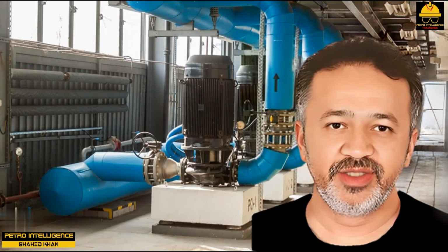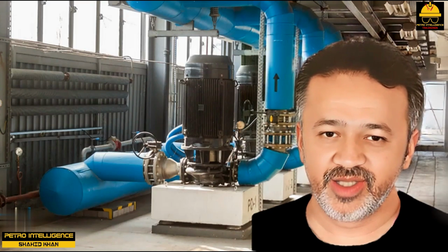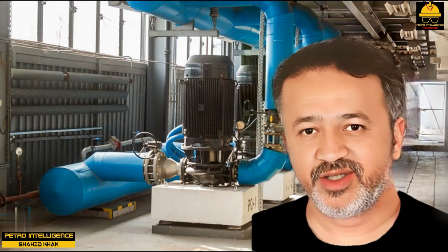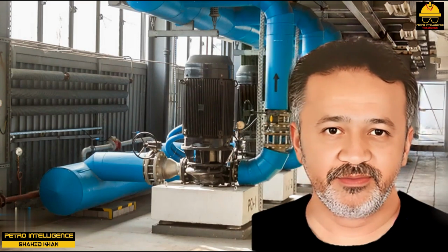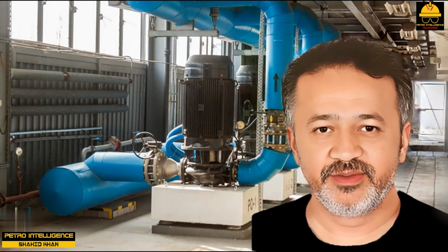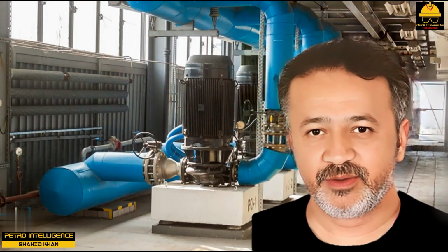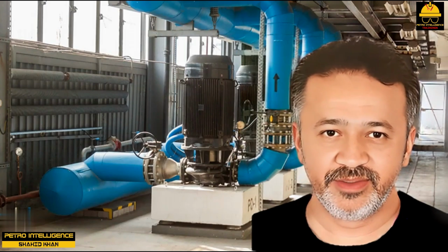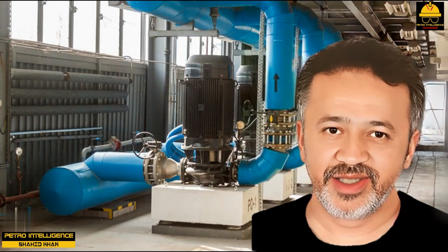An easy way to witness hydraulic surge for yourself is to install a pressure gauge at the suction of a centrifugal pump. Then shut down the pump. You will note a brief, but definite increase in the pump's suction pressure. This is the opposite of the effect I'll now discuss.